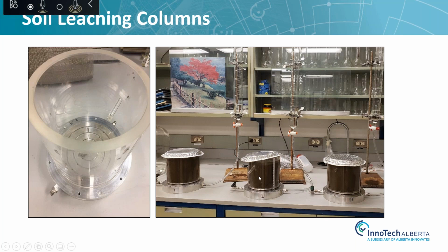In this case, it was 3 sequential events. Looking at parameters that would solubilize, the water was added and left for 1 week, and then drained, and that was done 3 times. So it's really understanding, over those flushing events, whether some of these parameters that we're concerned with here would essentially get flushed out, or whether there'd be an ongoing source.